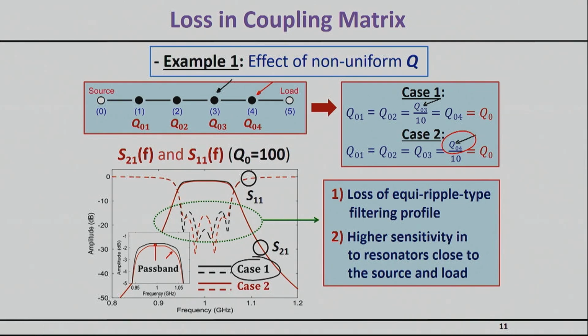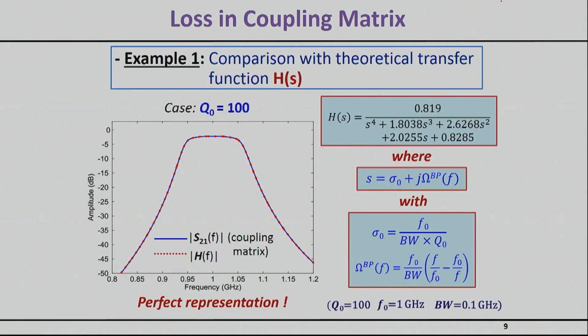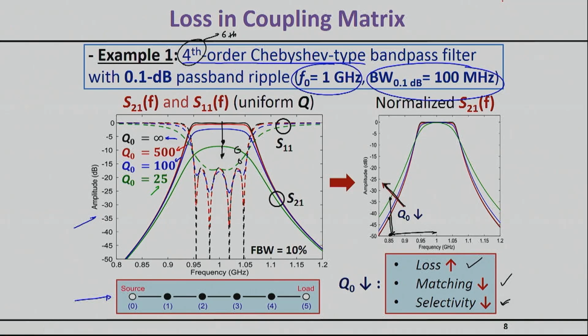Now, even more interesting than that, I think, is the question of why people might bother creating uneven Qs. This essentially has to do with fixing the transfer function. What I mean by that is, as you might see here, when you penalize the Q, you basically destroy the transfer function of the filter by penalizing its selectivity. By unevenly distributing Q, you can get some of this back.